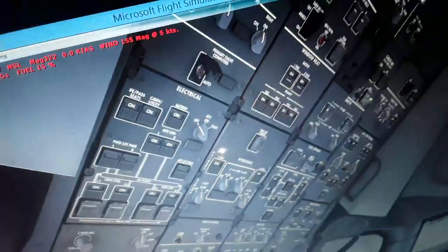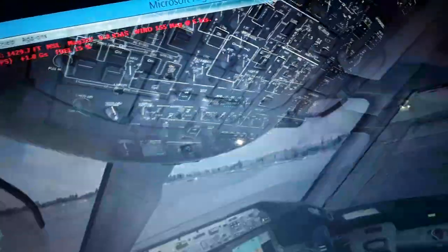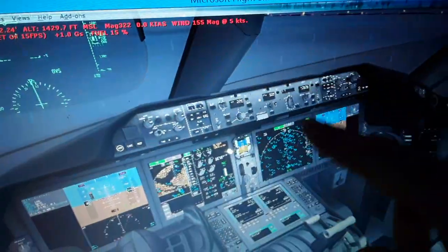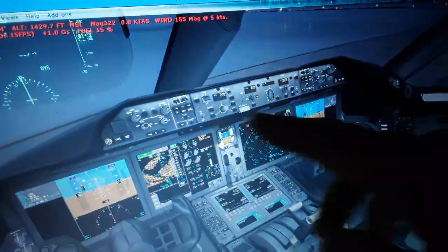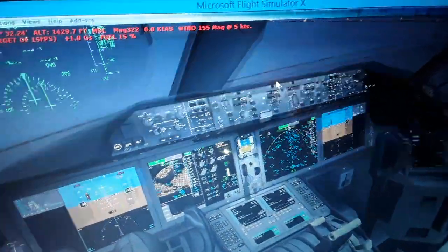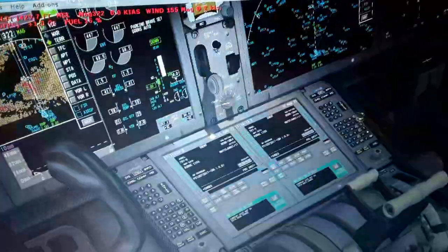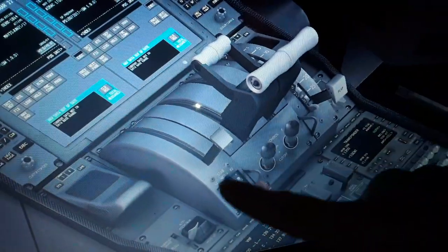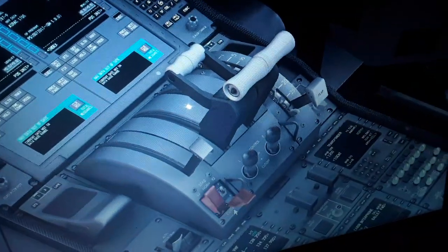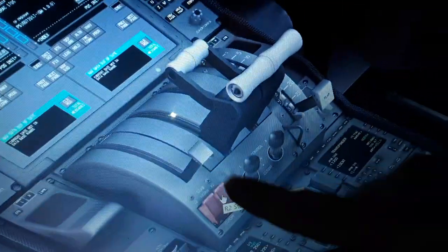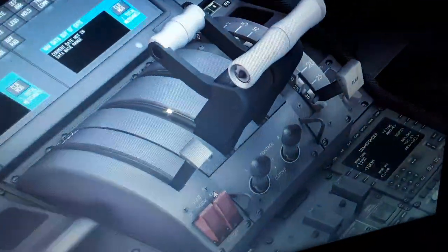So if we have a failure of the flight control computers, the mode will degrade. We're going to lose the automatic trimming. Also this will affect the autopilot engagement. We may lose the autopilot function and the flight director. So we have to come down here. This is for all Boeing 737, Boeing 747, Boeing 757, Boeing 767, Boeing 777 and Boeing 787.